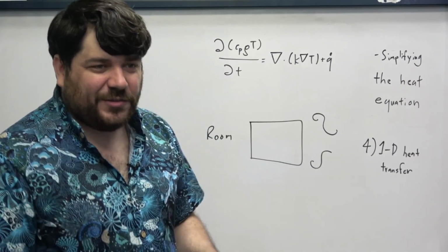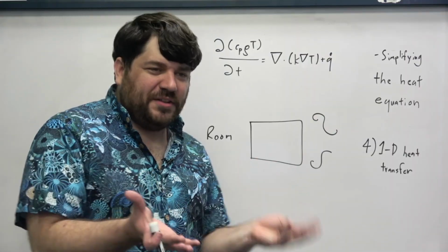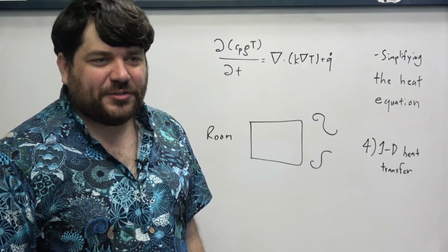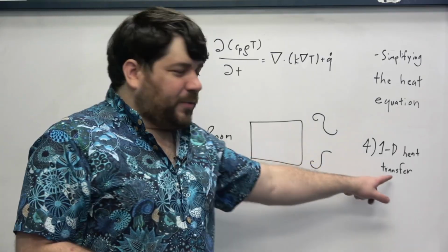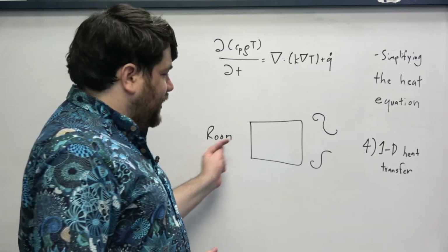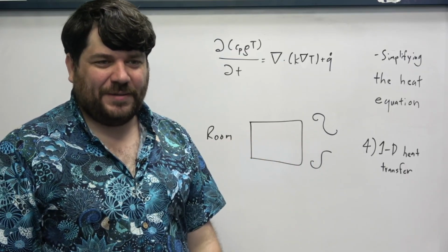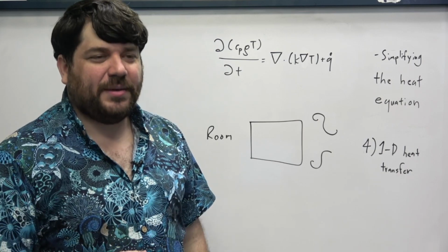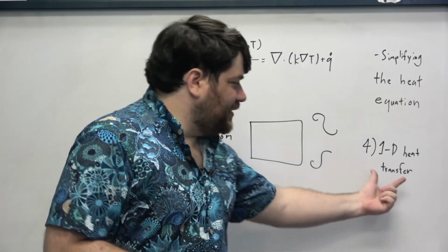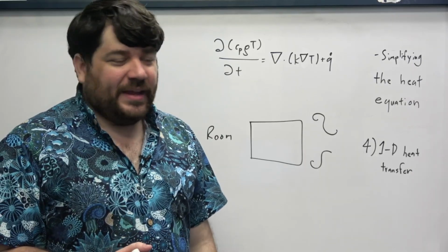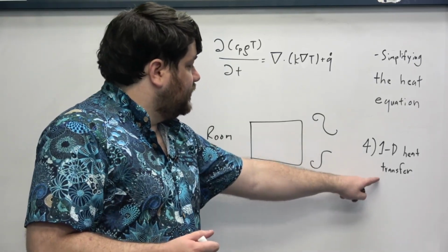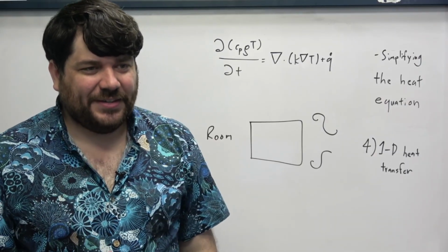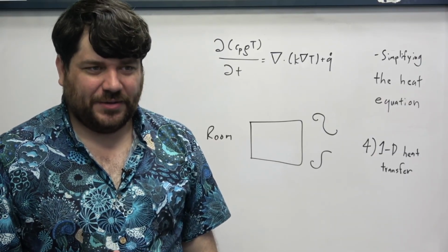And so it makes sense to say, well, we have a privileged direction in which heat transfer is occurring inside of this particular exercise. And so we're just going to assume that heat is only being transferred in that one direction, okay? And we've been implicitly doing this for a bunch of different examples that we've worked on before. It's just now we can directly say it. And the way that this approximation affects this actually depends on the geometry in the coordinate system that you're using.